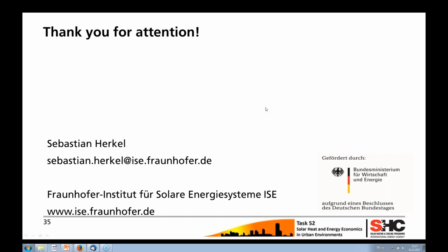Yeah, I can try to do it. I think what you see is that the actual costs of solar thermal are starting, let's say, around 1,000 euro per square meter if you go for the small systems, and you are going down to let's say 200 or whatever euro per square meter. For the exact data you have to look at the report of IEA Intake. So you have big price differences. And if you look at the levelized cost of heat, I think it starts around 150 euro per megawatt hour, and it goes down to, let's say, 35 euro per megawatt hour in the large Danish systems.